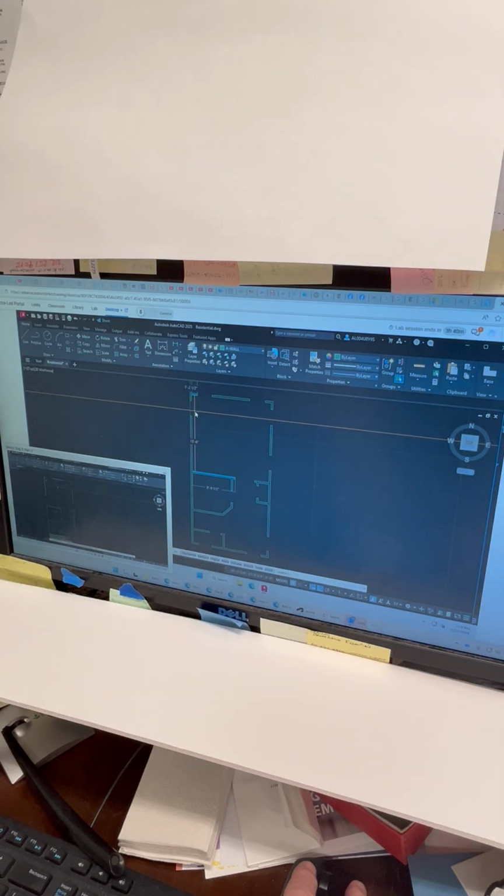As I move my mouse within this area, my crosshairs intersect other elements. And those elements highlight. So it lets you know what it's measuring to. And along the sides of the highlighted lines and entities, it shows a dimension for that.